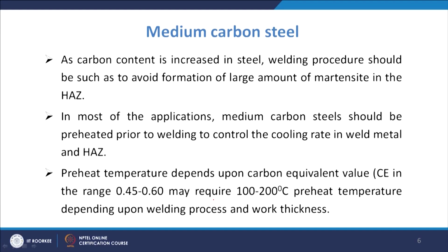So, as you see, when you further increase the carbon, that is defined as the medium carbon steel. Since you increase the carbon, the hardenability is increasing, so you are expecting the formation of martensite, which is a very hard and brittle phase, and you try to avoid it.